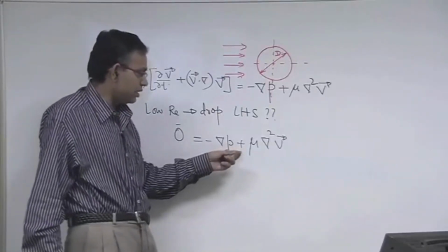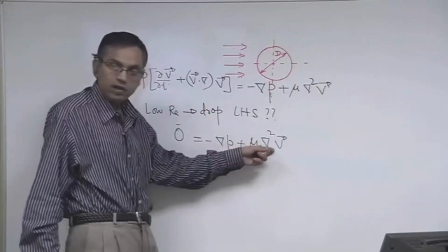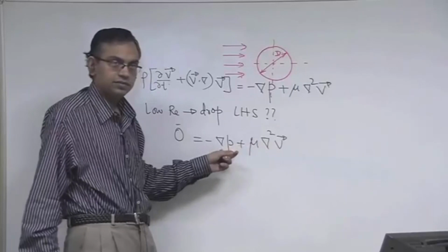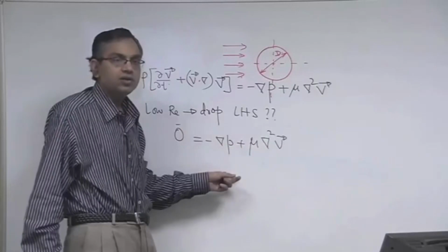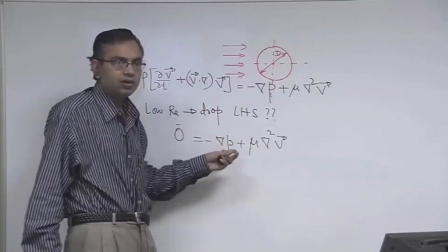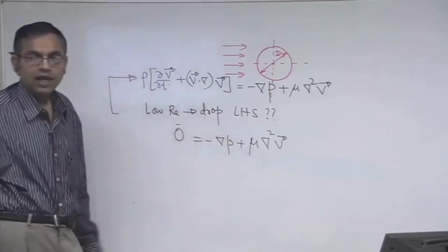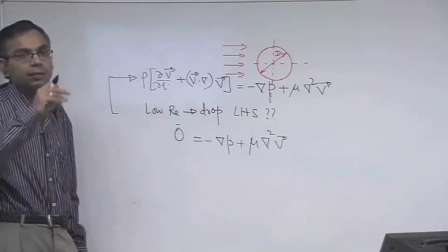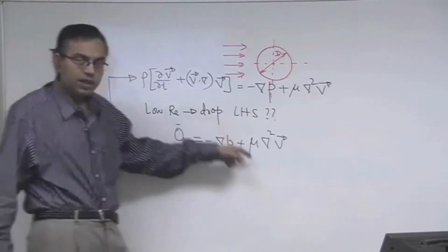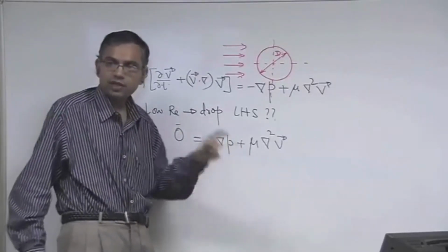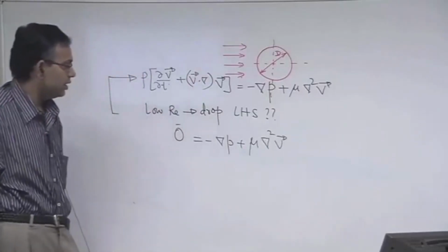So, this equation involves how many unknowns? In general 3 velocity components and pressure. So, you have 4 unknowns, and for an incompressible flow you have 4 governing equations also. So, that closes the system, but analytically it is very difficult to couple the continuity equation with what? With the momentum equations, with the Navier-Stokes equation. Analytically difficult to couple, numerically it is relatively more convenient.